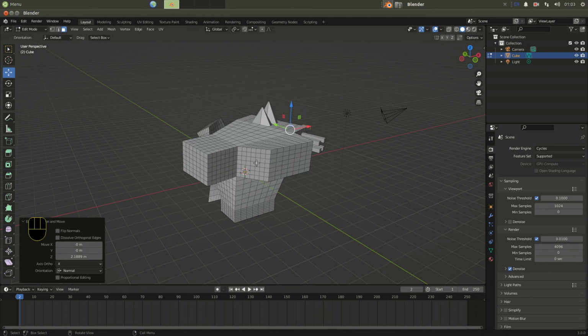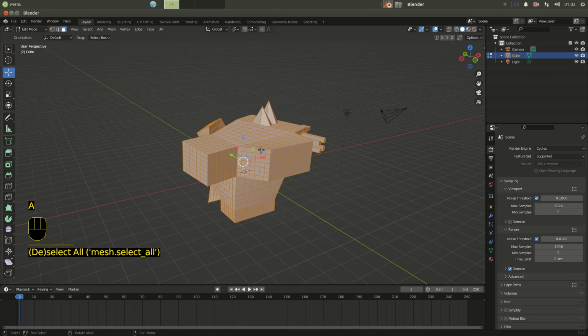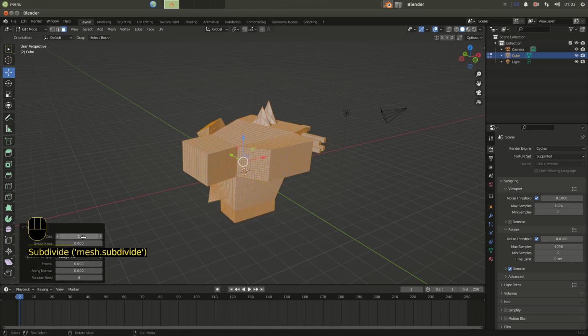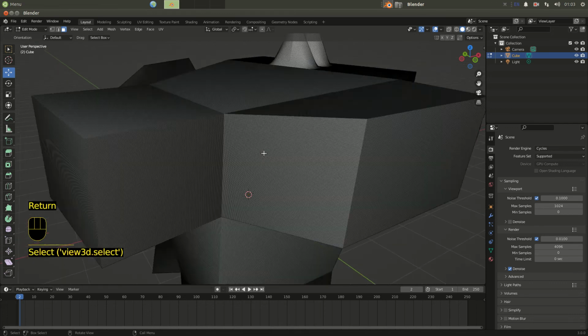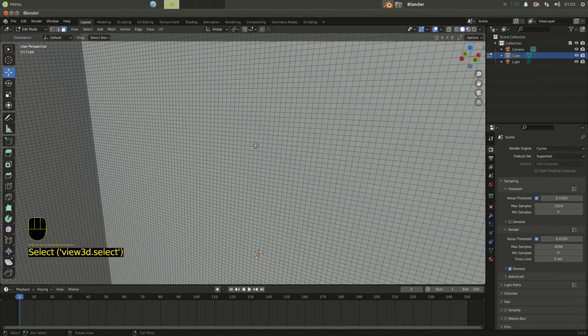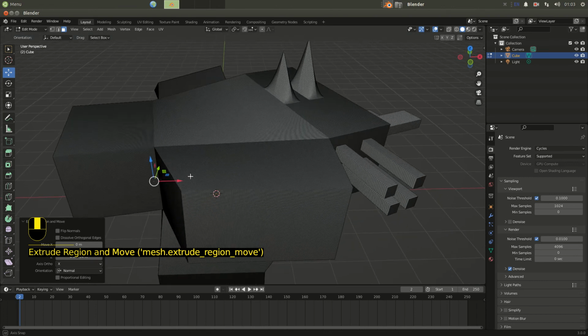So the more of these you have, so if I do something very silly like this and go right click, subdivide, and turn that to say 40 or something, and it's going to take a long time. And so I've got lots and lots of little subdivisions in there. Now what that means is those subdivisions are all there. There's one of them, and it's lagging down my computer, even though my computer's pretty fast. So I got far too many subdivisions in that.